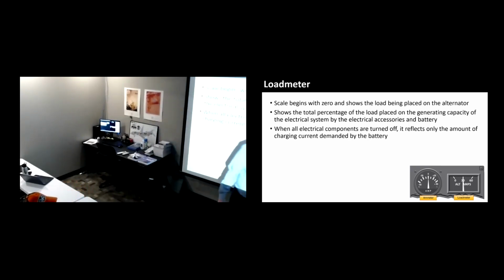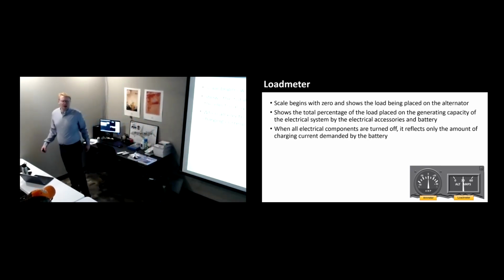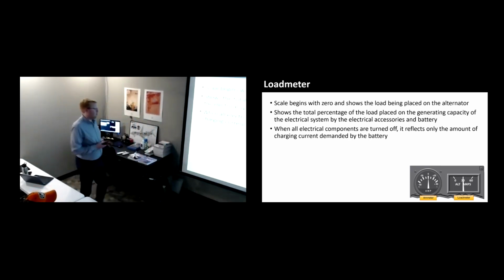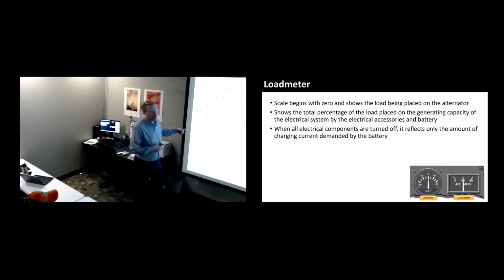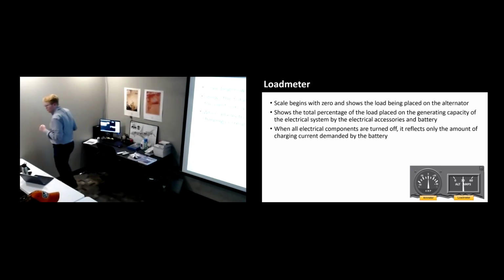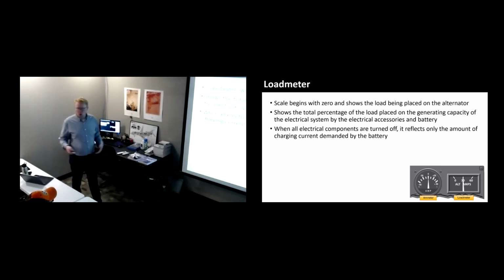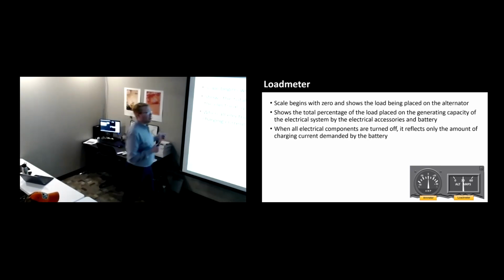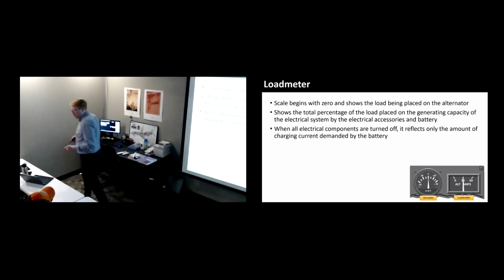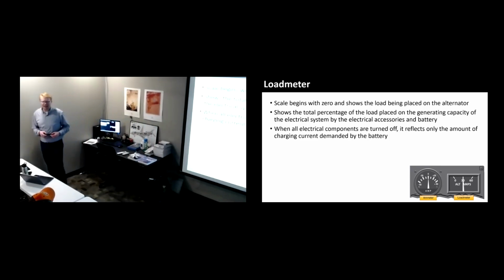At what point do you think, well, let me give you a scenario. We're sitting on the ground, airplane shut off. We walk up to it, we turn the battery on, right? The master switch, battery alternator, we turn that on. What gets powered? Almost everything. Lights, the bus, most of our primary buses. Usually an avionics bus won't get power from the master battery. You'll usually need to have a separate avionics switch for that one.